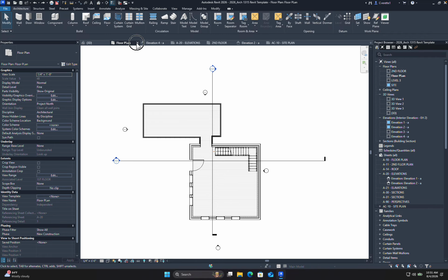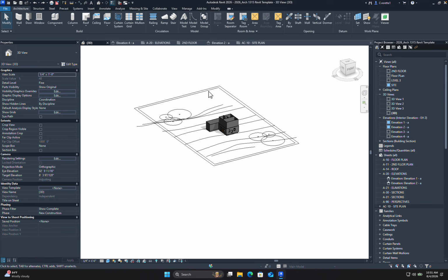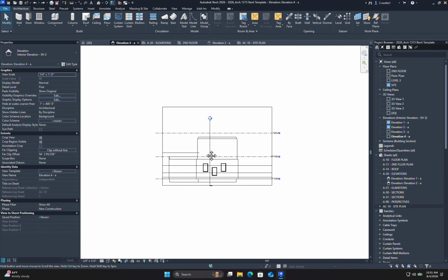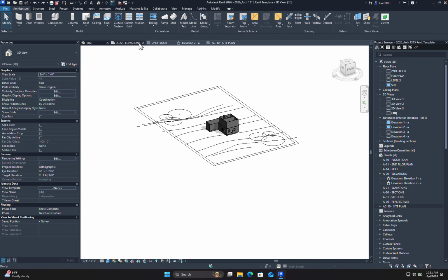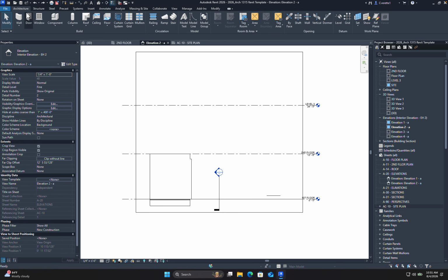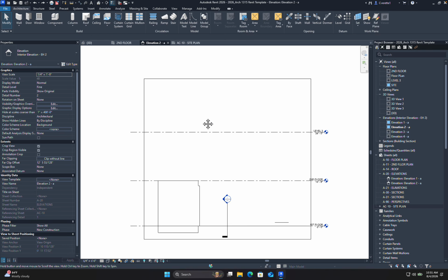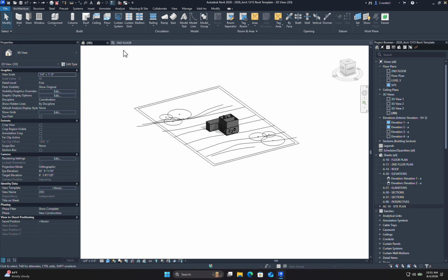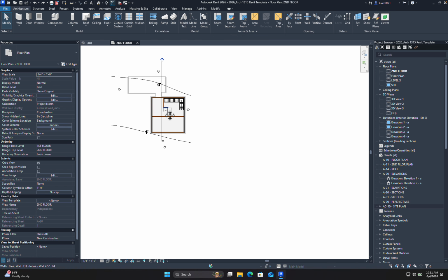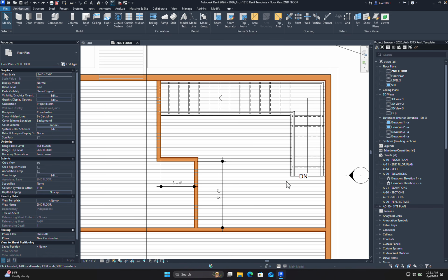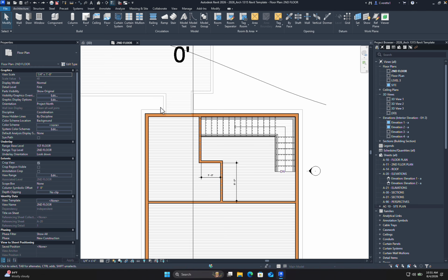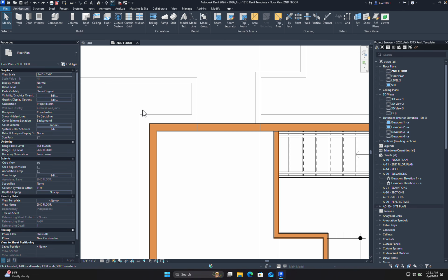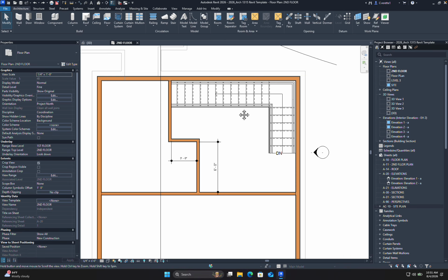So in our case, just to recap, we went over some of these project views, and yes, I should save. We went over how some of these viewports actually work compared to how they are on the sheet. We went over some of the tab information, such as the way that we input stairs and the way we input floors and doors, windows, these kinds of things, that they're all categorized. We went over elevations, site plans, and how to get them onto each other. We started designing and went over some of the minute things of modeling. How to control the model, how the model moves, and essentially things in between.